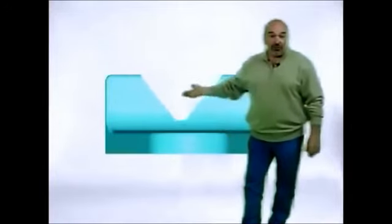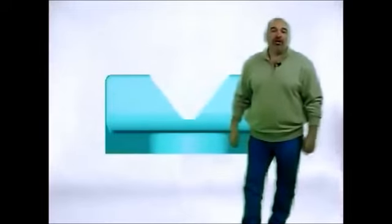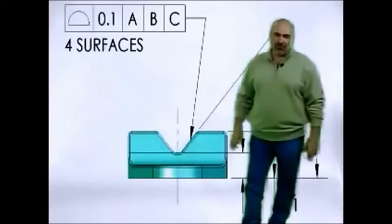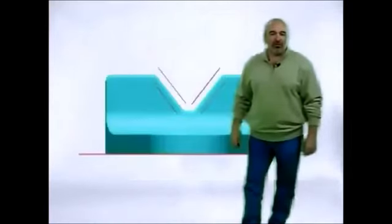The angled surfaces on this part, for instance, need to be located relative to the datum reference frame. If angularity had been applied, the drawing would be incomplete. Profile of a surface locates the surfaces in addition to controlling the angularity. The angled surfaces of the V block cannot be tipped more than the profile of a surface tolerance of 0.1.